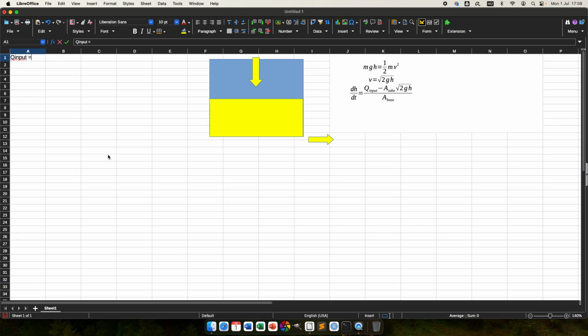The input should be in liter per hour. This is a common unit how they are measured. For example, 800 liter per hour, it is the value how we can see the water coming out if we open the tap completely. But we need the calculation in meter, so it should be cubic meter per hour. So this will be divided by 1000 because 1 cubic meter is 1000 liter.